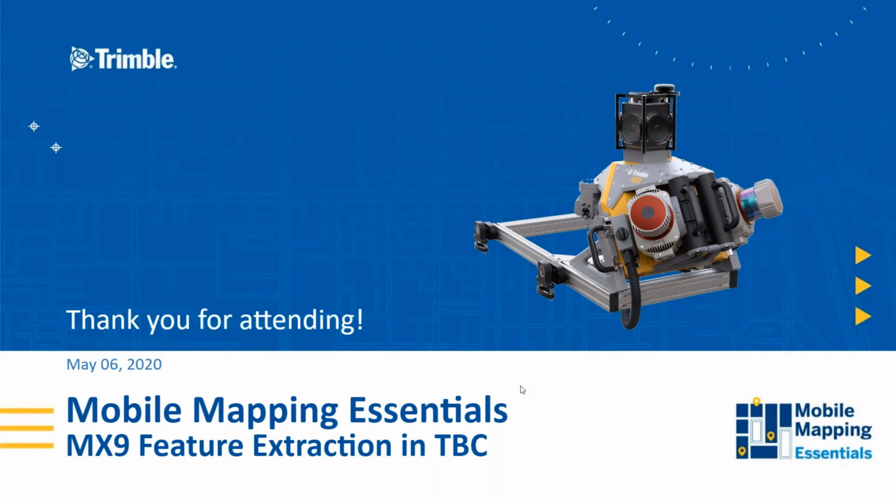Oh, I see. So for the feature extraction you're talking about the point extraction, the trees and poles command. Now I understand your question. For that command, we actually recommend you go through the point cloud classification first, because that will help TBC filter out some unnecessary noise in the point cloud and really focus on the good data.